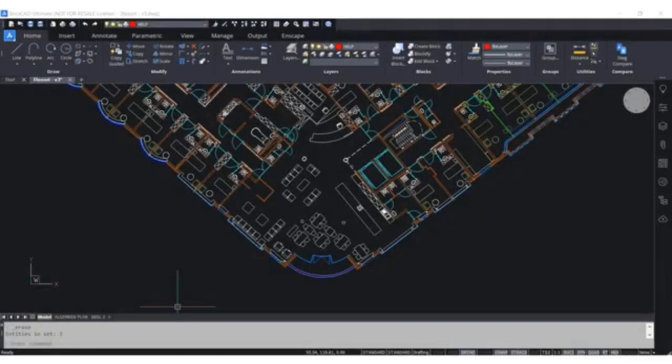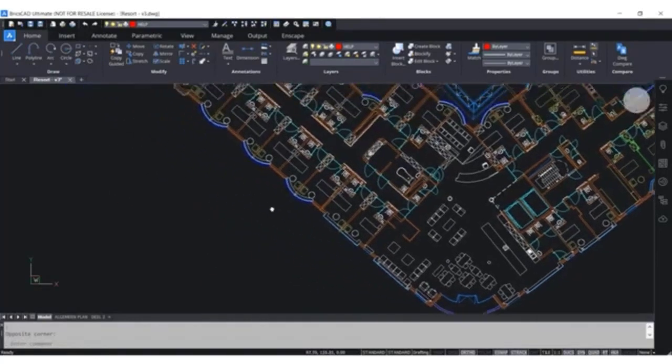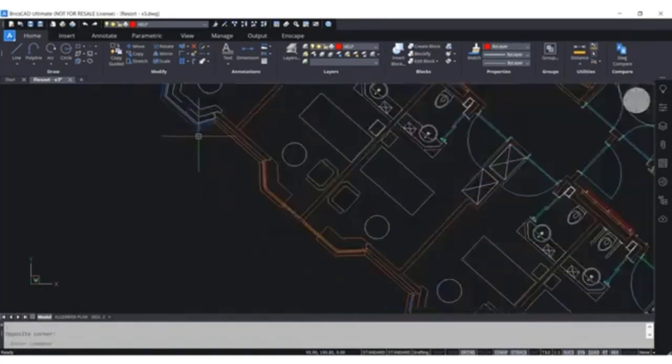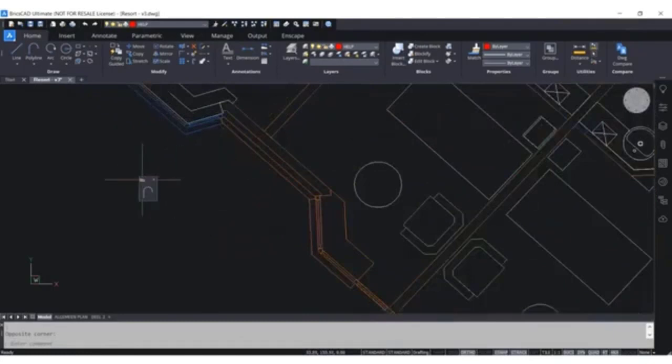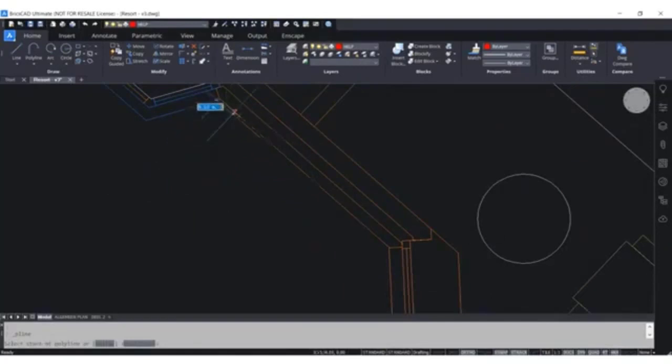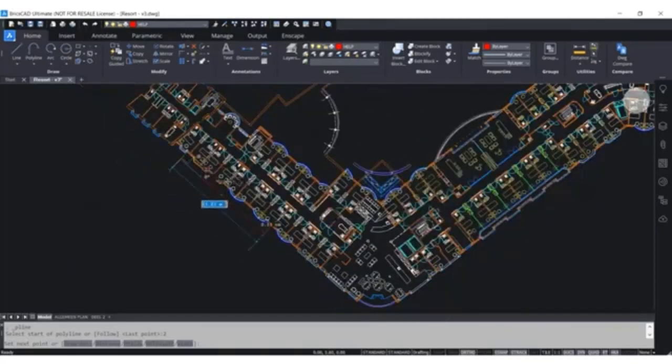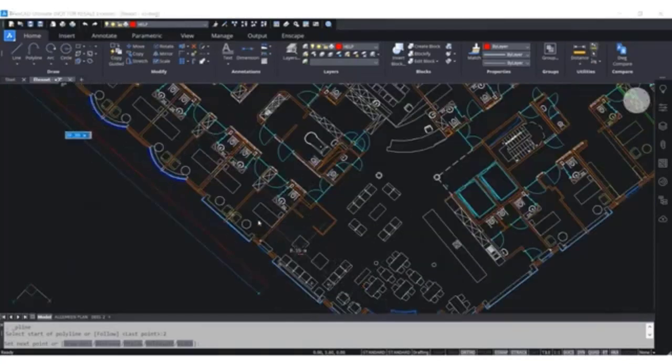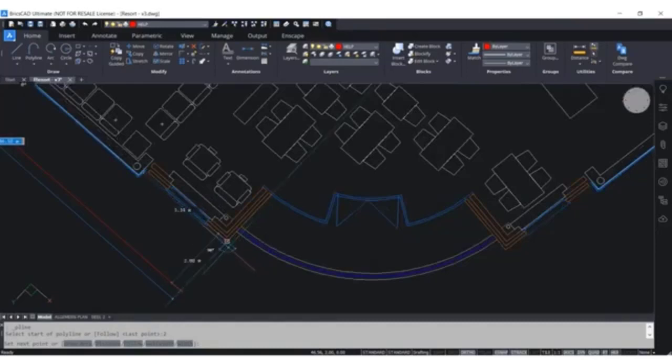In V20, the dynamic input and its grid have been enhanced. With the adaptive grid, snap, and dynamic input active, I can draw the road in a few easy steps. I'm going to select polyline from the quad. Hover my crosshair through this line so I can temporarily change the UCS. I'm then going to click Shift, then Tab, and key in 2 meter offset from the building. Then Enter, and I will go to the second point of my road.